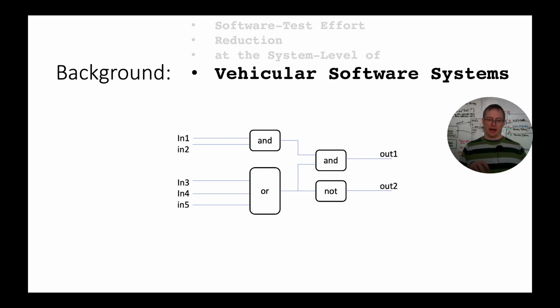Then you have a number of elements that you compute the output from, and then all of the outputs are computed and presented at the same time. So this means that every 64 milliseconds you recalculate the results of the outputs from the inputs. And this gives a much more precise determinism than you have in a desktop system. Also, if it's really, really critical, it's much easier to create mathematical models to verify that it will work. Awesome.